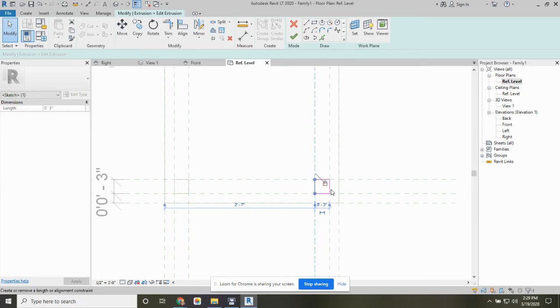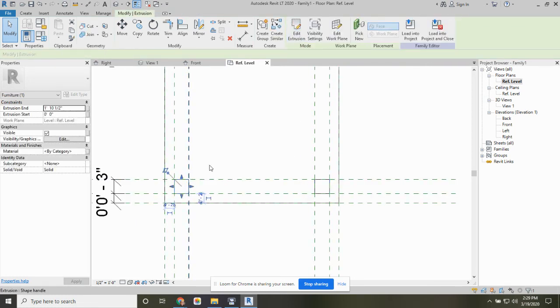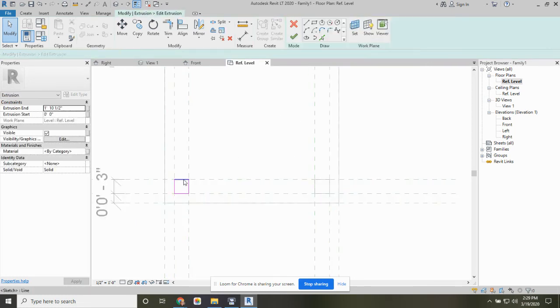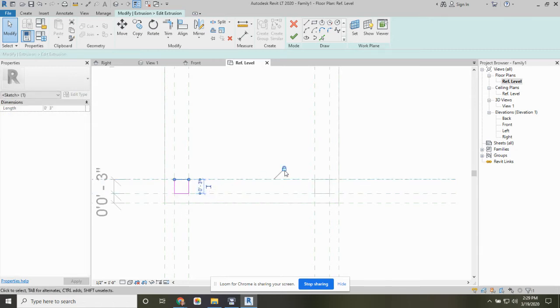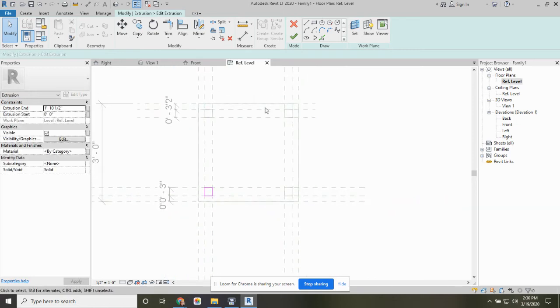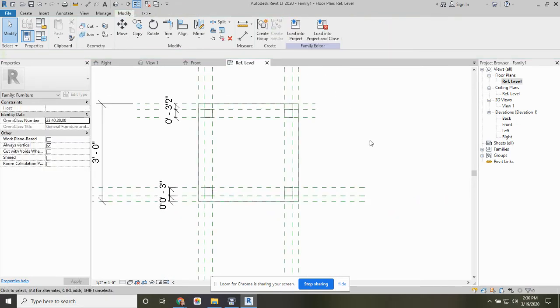And if you forget to do this, you'll find out when you get into doing the parametric modeling part of it. You're going to find out pretty quickly when the table breaks because you start moving it or flexing it. It kind of doesn't do what you expect it to, and you realize you don't have it constrained properly. So even though I'm not making it parametric yet, I'm thinking about maybe making it parametric in the future. So I'm thinking about the best practices to use to make sure that that model comes out right.